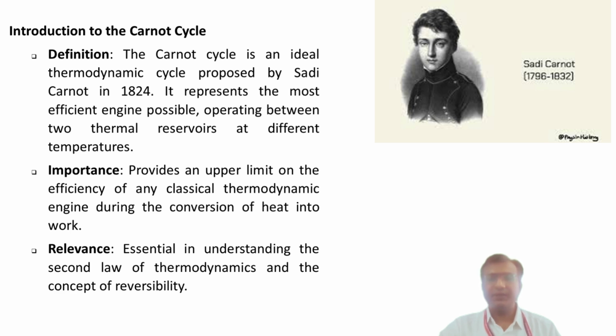So earlier there were the heat engines. So what are these heat engines? It is a device that converts heat into mechanical work. The efficiency of a heat engine is defined as the ratio of the work it produces to the heat input it receives. The Carnot cycle shows that there is a maximum possible efficiency for any heat engine operating between 2 specific temperatures, and no real engine can exceed this efficiency.